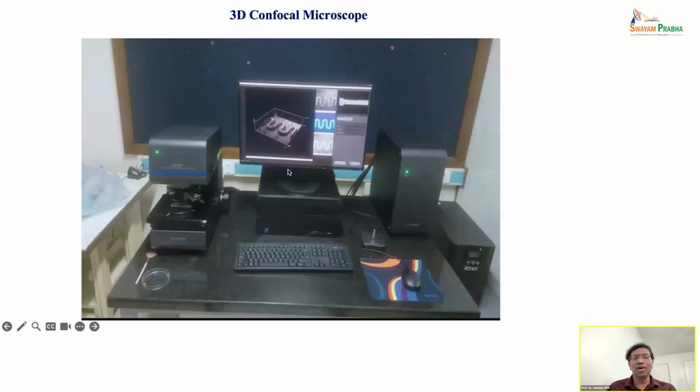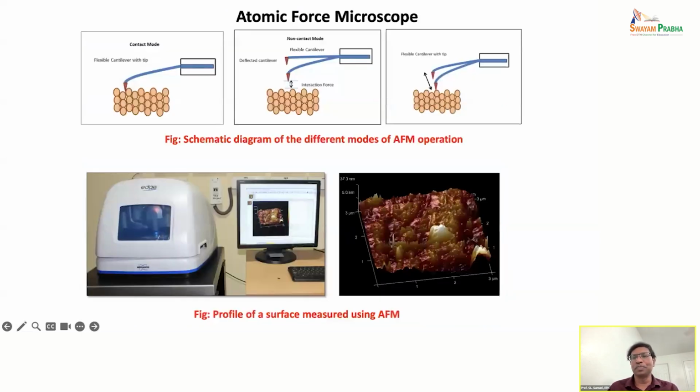So the confocal microscopy is an interesting principle, where there are piezo actuators, and every time the height changes, the piezo actuators move the lenses to focus. The amount it has moved is the information used to reconstruct the actual profile. Thus we get very, very clear images by using the confocal microscope.